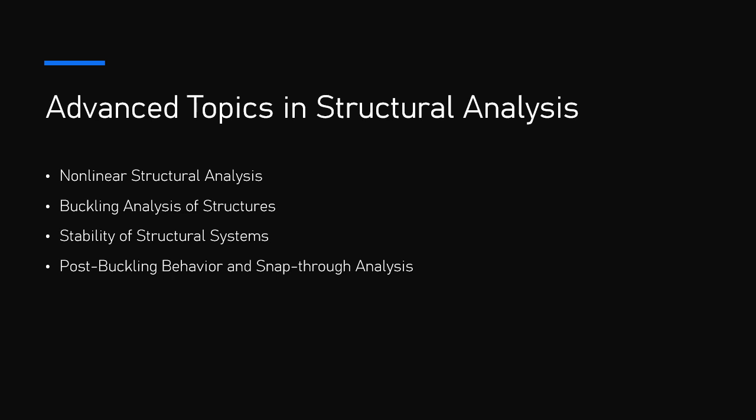2. End conditions. The type of support or boundary conditions at the ends of the structure, e.g., pinned, fixed, or free, plays a critical role in determining the buckling load. Pin-ended columns allow rotation and displacement in the direction of the load. Fixed-ended columns prevent both rotation and displacement, leading to higher buckling resistance. Fixed-pinned or free columns offer intermediate resistance, depending on how the load is applied.